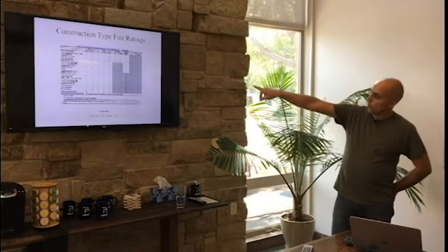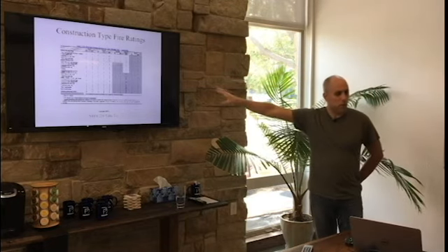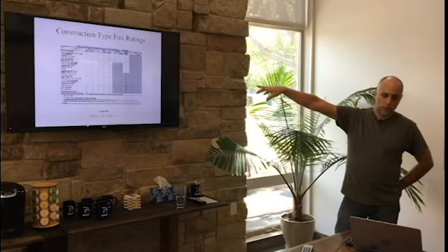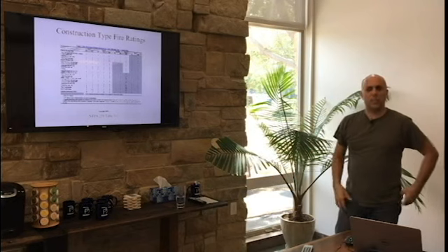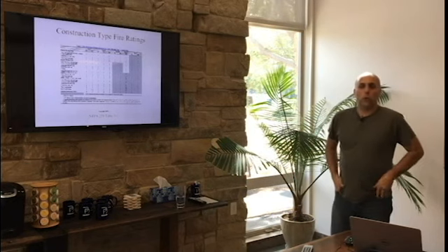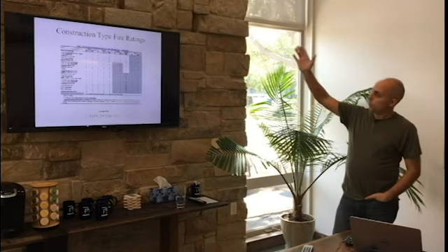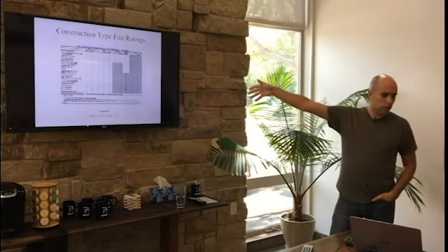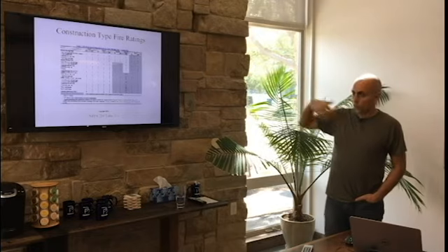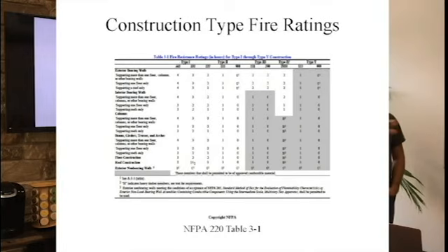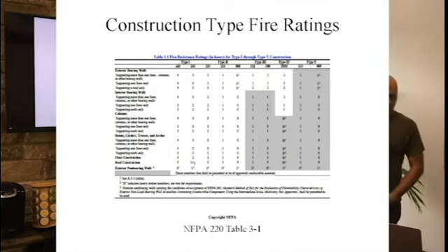Any of the areas that are in gray are allowed to have combustible materials in the construction of them. If it's not in gray, it's totally non-combustible. You can't have anything combustible. Structural or not, it can't be combustible in the building. So type 5, you have unprotected, which we call 000, and type 5, 111. Don't get caught up on the 110, 211. You go by the chart. Whatever it says you have to do under the type, that's what you do. It just uses the nomenclature.